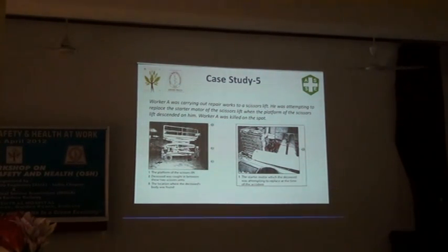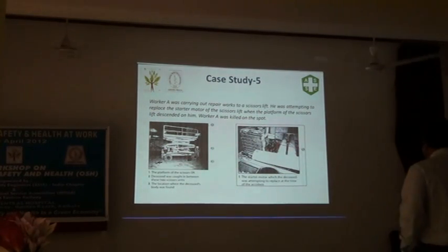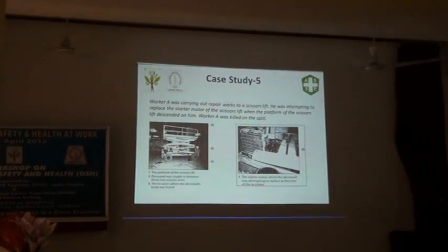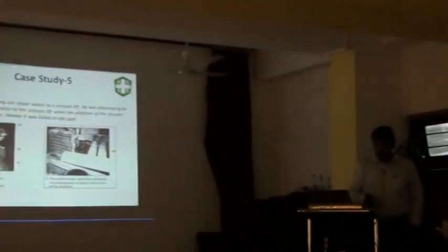So what is LOTO? Lockout tagout. What is the purpose of LOTO? Positive isolation. Good. So looking at this, the first thought that will come to my mind or anybody's mind is we did not operate with the LOTO. LOTO is actually a hazardous energy control procedure. We are blocking the source of hazardous energy from the source to the equipment. So by means of positive isolation, by removing the energy from that.